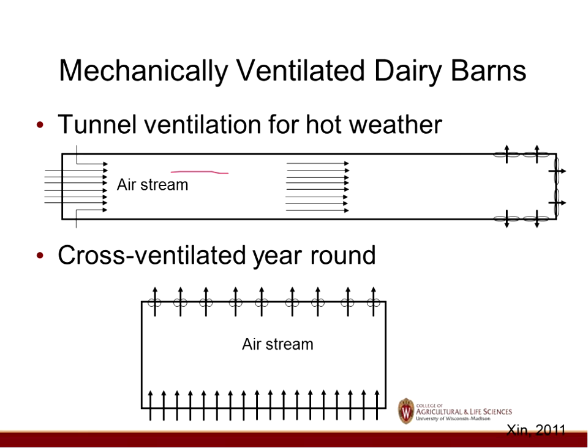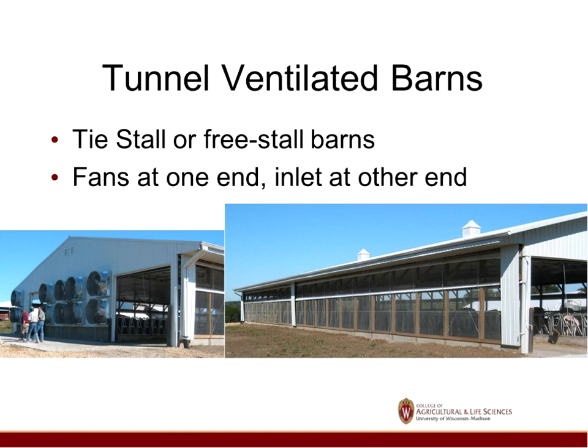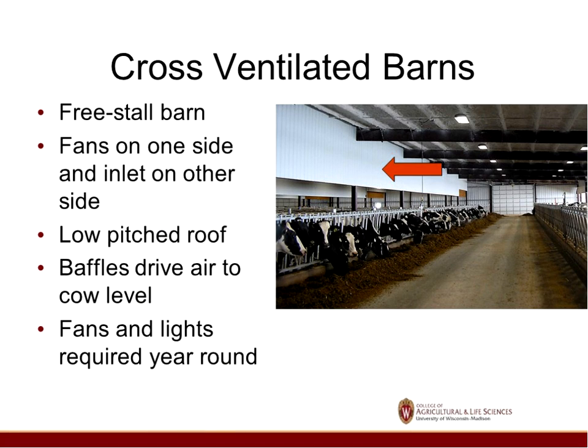Tunnel fans are very often used, so you can take a stall barn and make it into a tunnel ventilated barn or a freestall barn. But cross ventilated barns are increasingly used. Well, here's a picture of a tunnel ventilated barn. They can have a curtain sidewall, and the curtains are pulled up when we want to tunnel ventilate, and the fan's on one end.